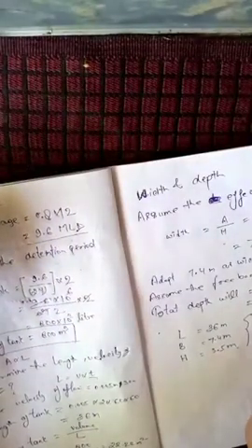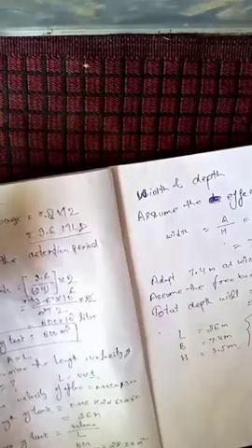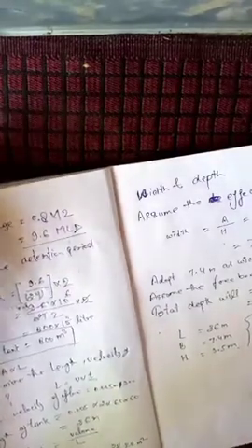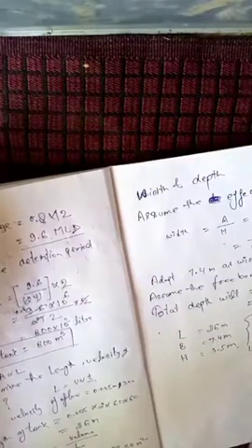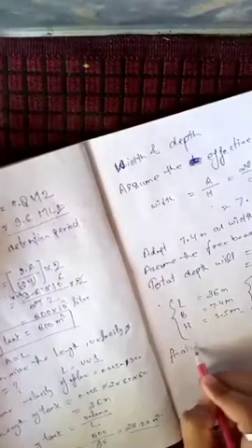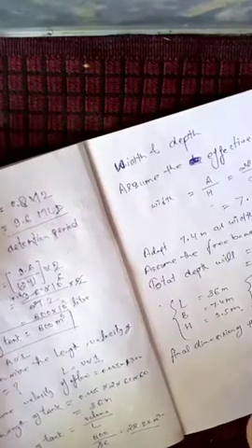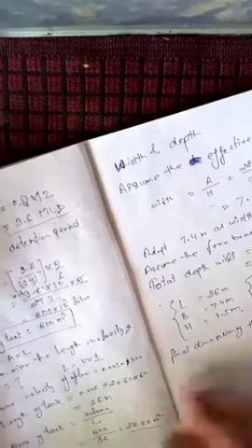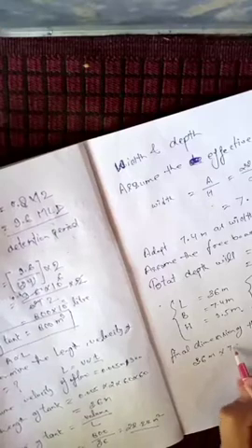First one, we have to check that depth. It must be between 2.4 to 3.6 meter effective depth. Again width must be less than 7.5 meter, and length will be 4 to 5 times. So all the parameters are correct, hence the final dimensions of the tank are 36 by 7.4 by 3.5 meter.